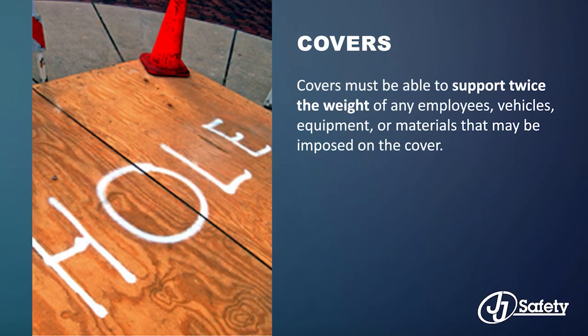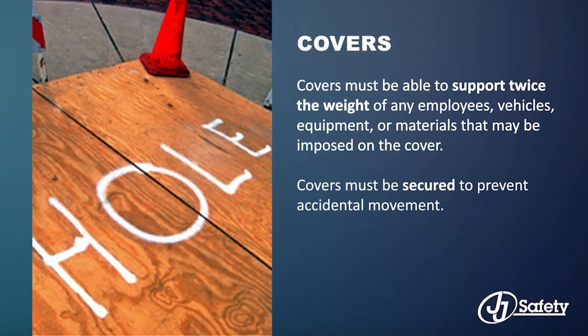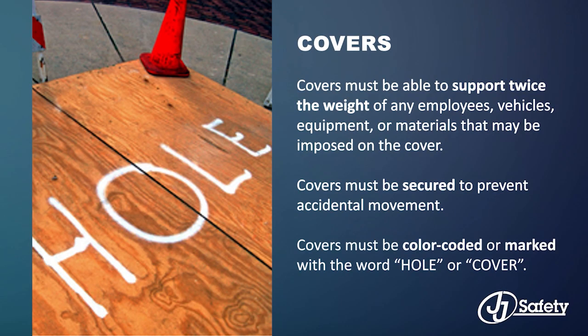Covers must be able to support twice the weight of any employees, vehicles, equipment, or materials that may be imposed on the cover. Covers must be secured to prevent accidental movement. Covers must be color-coded or marked with the word hole or cover.